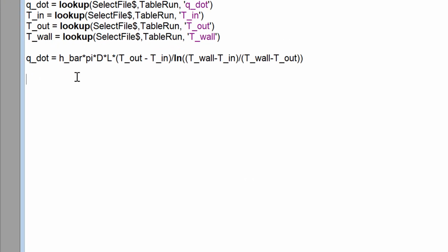I think the last thing that I'm supposed to do here for calculations is figure out the Nusselt number and the Reynolds number, and to do that I'm going to need some properties. So let's go ahead and get the density of my fluid at T equals T. So I should probably use the average temperature, so I'll calculate that here in a second, and P equals P. So the average temperature of the fluid is T out plus T in divided by 2.